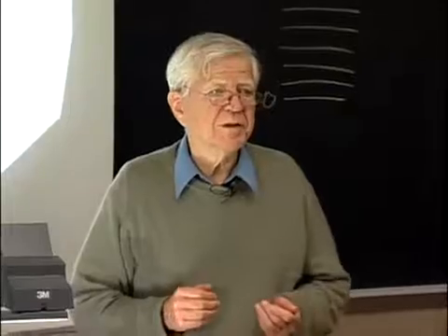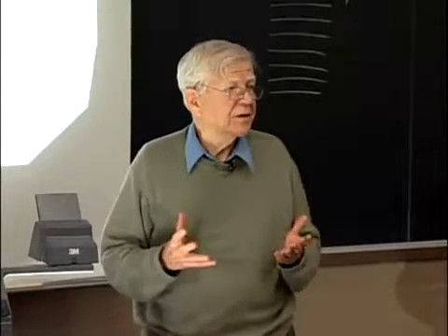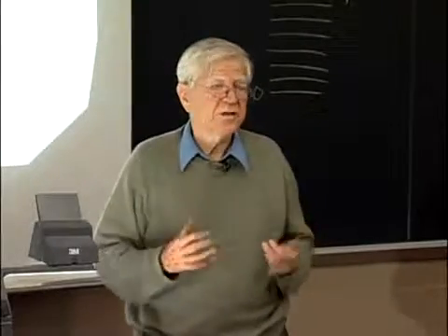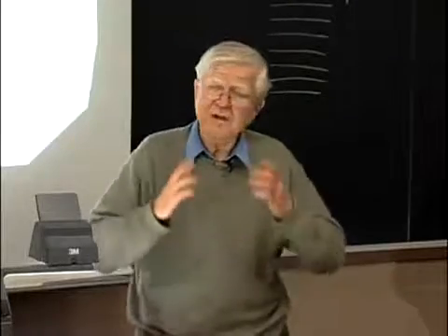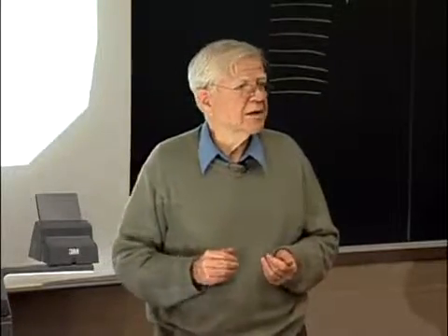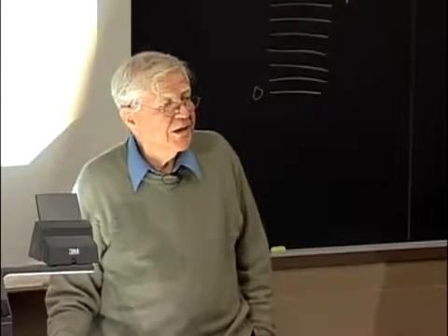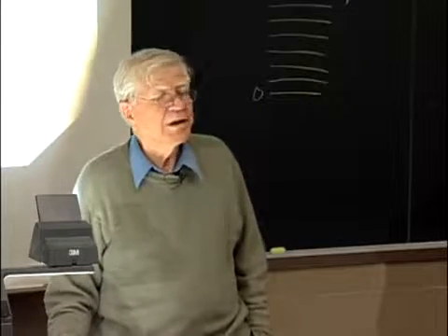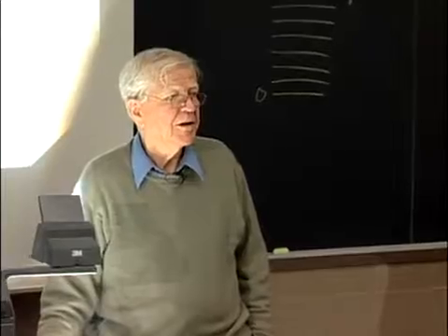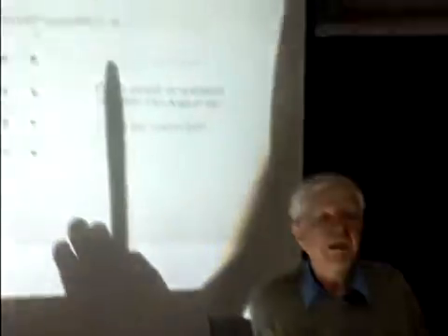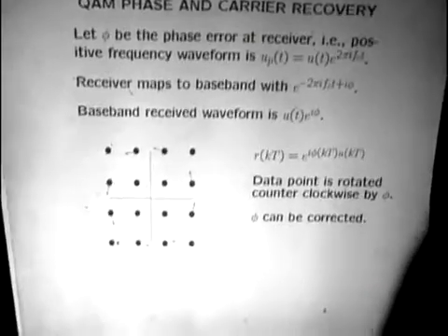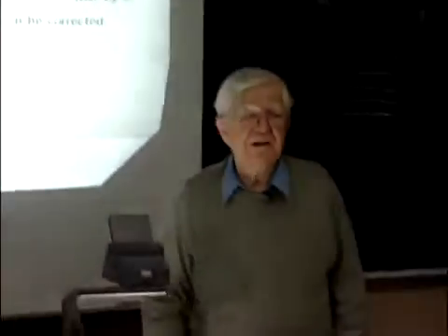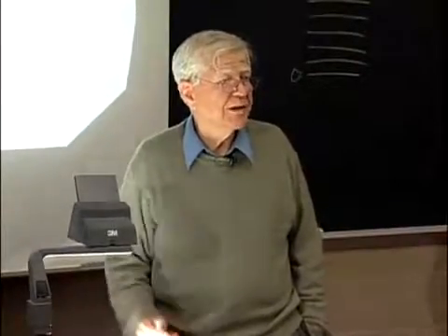When you average over a long period of time, the noise is sort of independent from one period to another, so the noise averages out, and the thing you see then is the phase errors. So long as the phase is slow and the noise is quick, you first decode the data. After you decode the data, you average over what the phase errors are, and then you go and you change the clock. And people spend their lives designing how to make these phase lock loops, and there's a lot of interesting technology there. But the point is, the idea is almost trivially simple, and this is what it is.